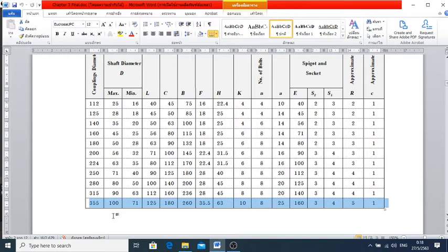For instance, you can apply a chain transmission, belt transmission, or gear transmission system rather than the coupling, because the coupling is too big and the weight is going to be too much. The shaft is going to be subjected to transverse loading, which will cause a lot of failure to the bearing consequently. So you have to be careful with this anyway, okay?